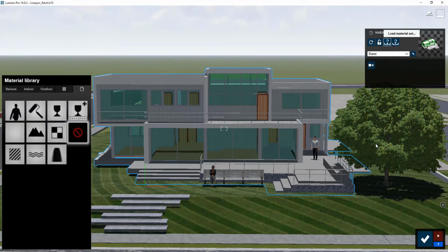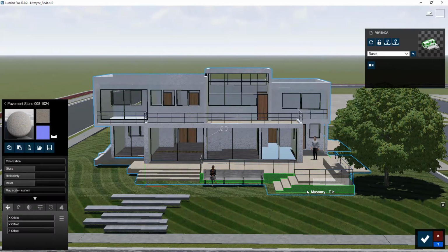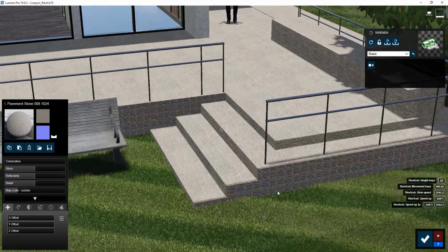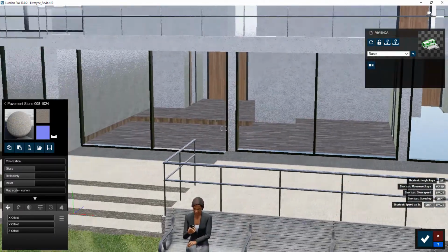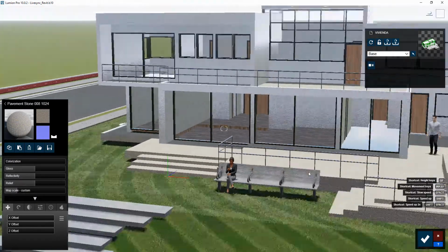Once I open that, it will detect the materials that I have configured, and these are the materials that will replace the current materials. So I'll just click on the override materials button. Okay, and then you can see all the materials have been replaced, including the flooring, the walls, the glass panels and the grills as well.